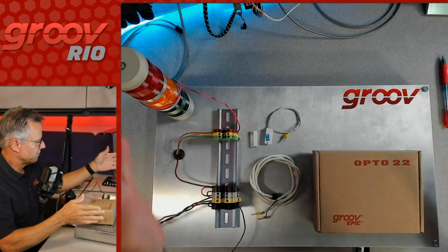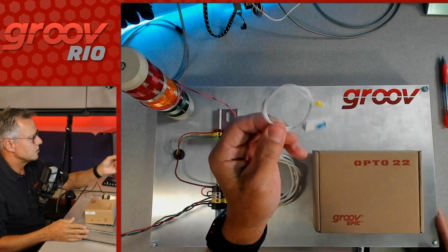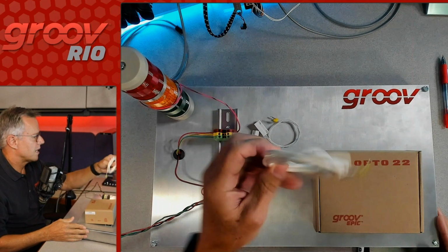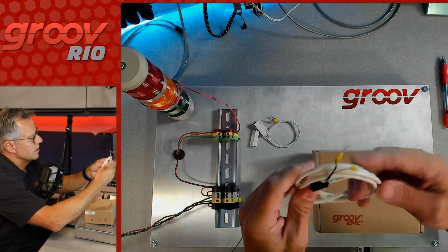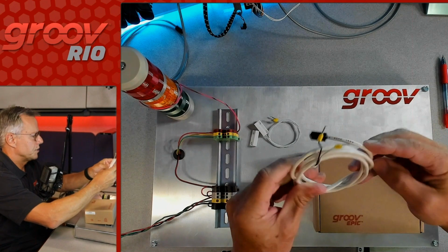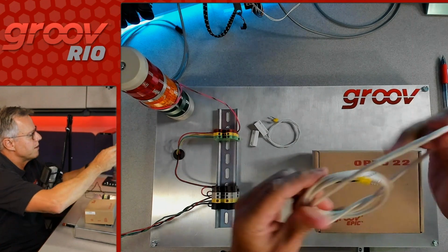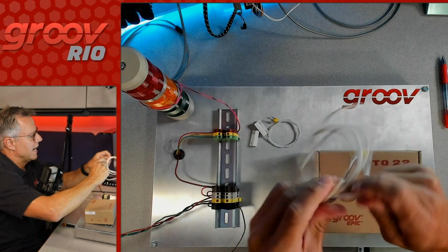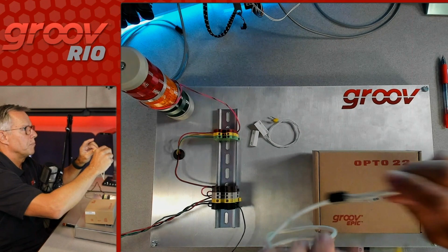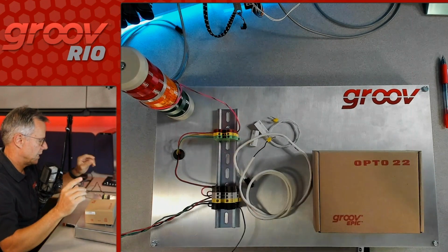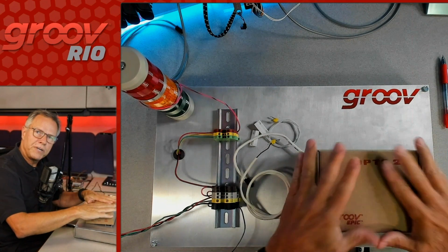And here I've got my stack light I described a moment ago. I've got my cool little door sensor here, and I've got an ICTD. An ICTD is an integrated circuit temperature device. And what's cool about these guys is they're just little 2-wire temperature sensors, and they can go a distance of 2,000 feet. So that's kind of cool, and it'll become important when Doug talks about his application that he's working on coming up. Then I've got my Rio right here in the box.